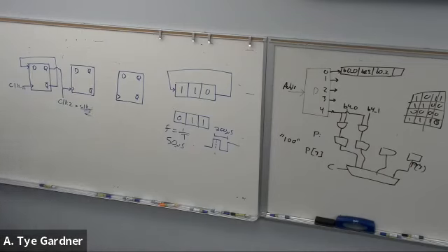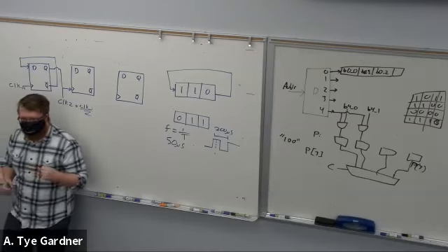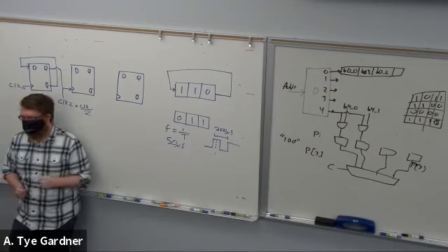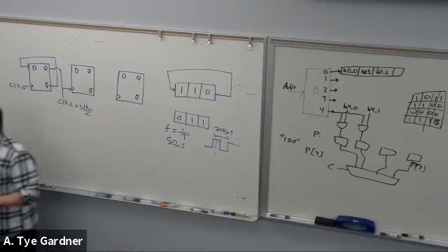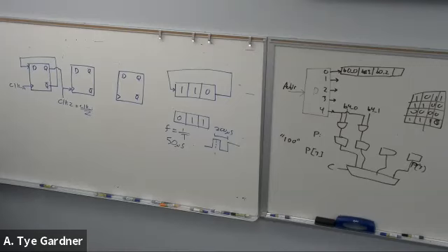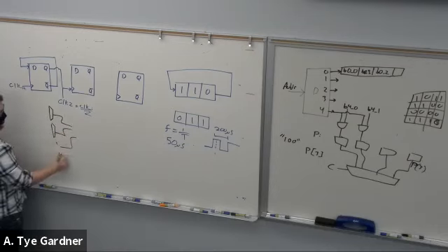Other questions that I might have around muxes, I could very likely ask something like, design me a 16-to-1 mux using only 4-to-1 muxes. And that one again, if you forgot, is I just take a 4-to-1, another 4-to-1, and 2 more, and I connect them up to another 4-to-1.